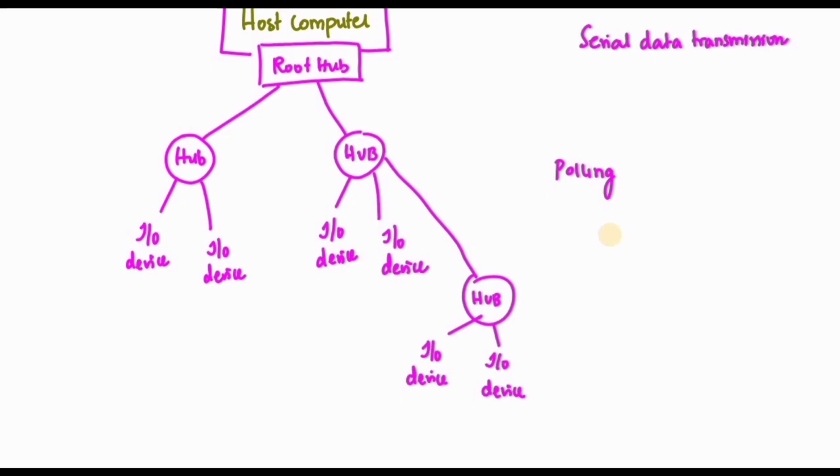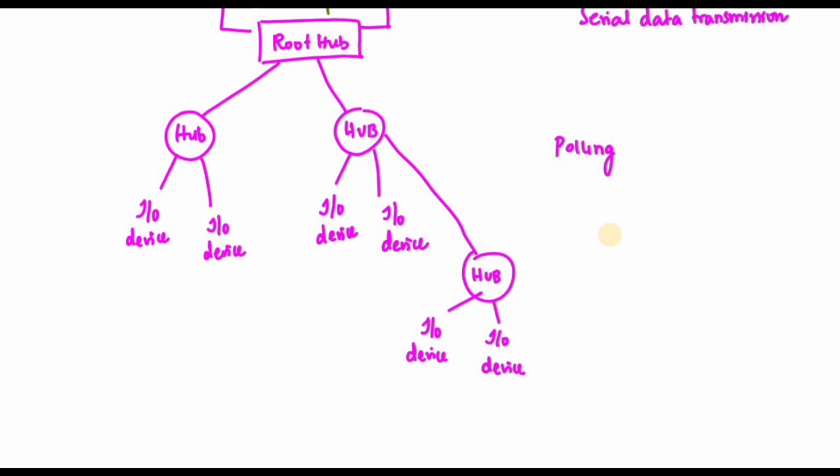USB can transfer data in an isochronous manner. Isochronous data needs to be transferred at precisely timed regular intervals. To accommodate this type of traffic, the root hub transmits a uniquely recognizable sequence of bits over the USB tree every millisecond. This sequence of bits is called the start of frame character, which acts as a marker indicating the beginning of the isochronous data transmitted after it. Thus digitized audio and video signals can be transferred in a regular and precise time manner.